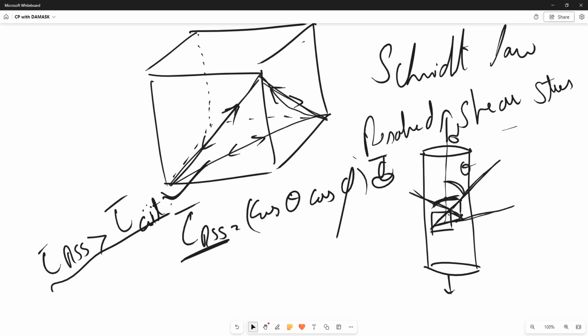It takes place according to a certain velocity gradient attached to it. So how fast will this slip take place? And then there is this hardening rule. So when will this slip stop taking place? We also have defined them generally for every slip system, and according to that the slip takes place, which means it is relatively easy to understand on a single crystal structure.